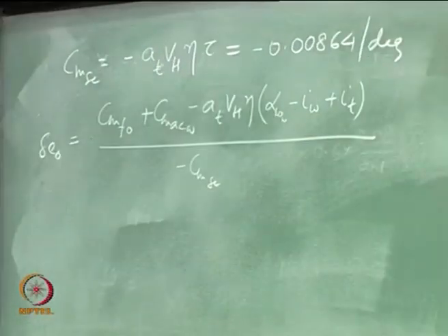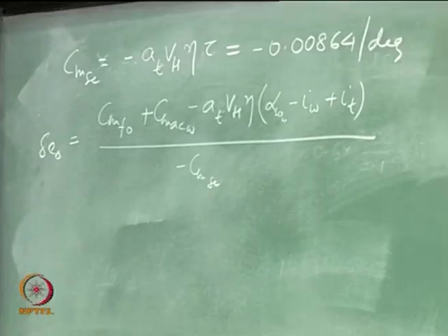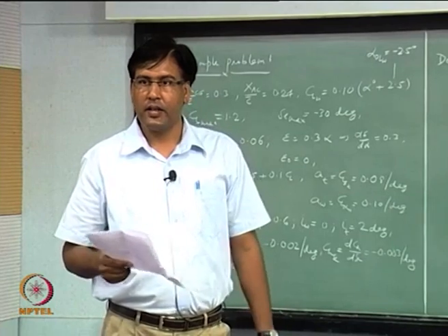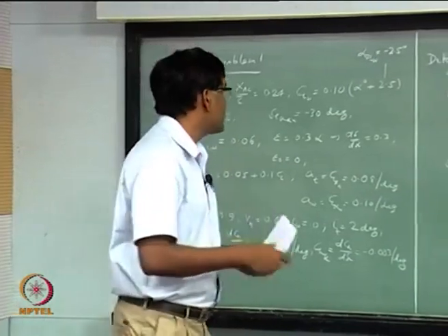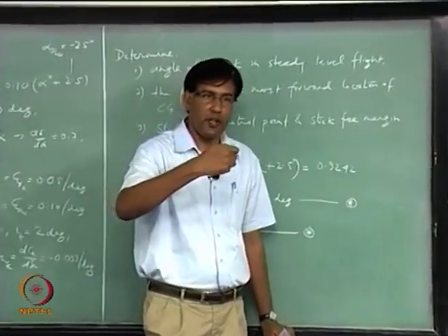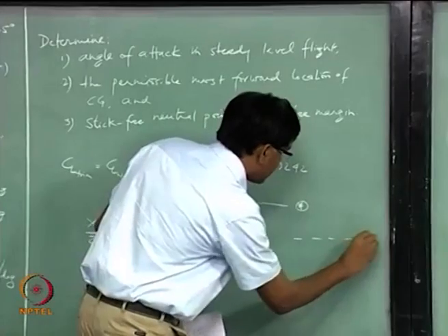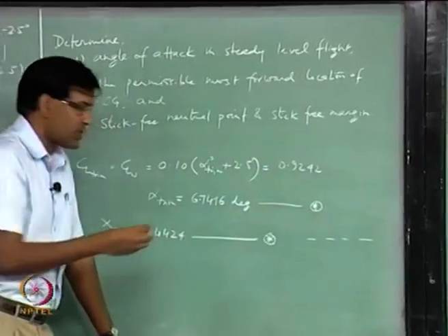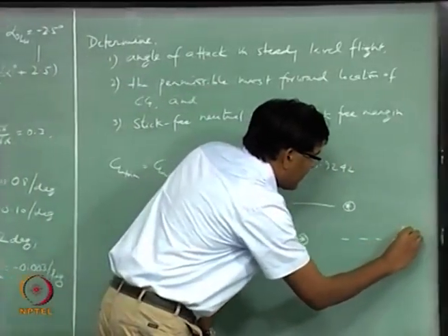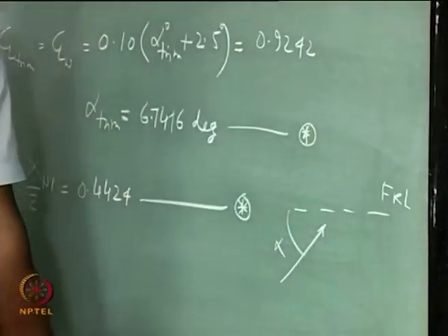Right, I am setting the alpha trim to 0, but still have this 0 angle of attack of the wing. So, alpha w here is now also including that alpha 0 LW. Remember we are talking about this, the fuselage reference line, and your alpha is this.